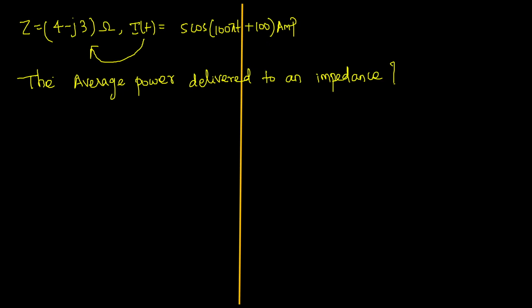In AC we have to calculate XL and XC; you should not go with the L and C parameters when we are dealing with the inductor and the capacitor. Those small basics are very important. If you don't remember them, it will affect you. So be careful while calculating the values.